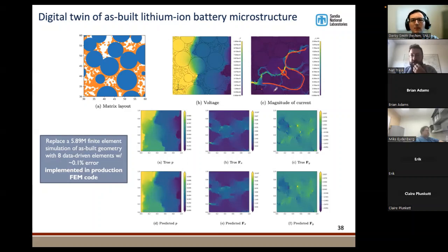So the challenge with actually modeling this is you need to design something at a continuum scale, but the failures are driven by this kind of mesoscale process. So what we do is we do a handful of these simulations. We have like 10 simulations of a given battery. We run it through this control volume analysis. It's identifying these pathways and fitting a model to it.